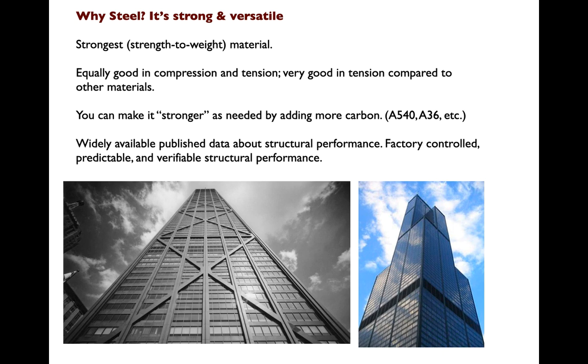Because that means that essentially when we're designing a beam, we can design it symmetrically if it's being loaded symmetrically, because compression and tension values in steel are relatively equal. Whether we turn a beam upside down or not doesn't really matter. There are very few other materials that we can say that about.